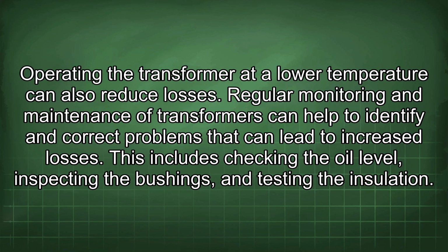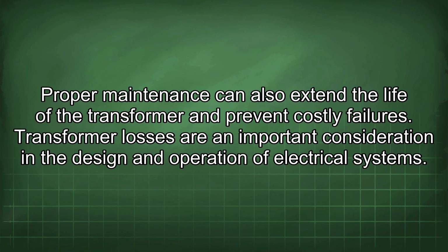Regular monitoring and maintenance of transformers can help to identify and correct problems that can lead to increased losses. This includes checking the oil level, inspecting the bushings, and testing the insulation. Proper maintenance can also extend the life of the transformer and prevent costly failures.